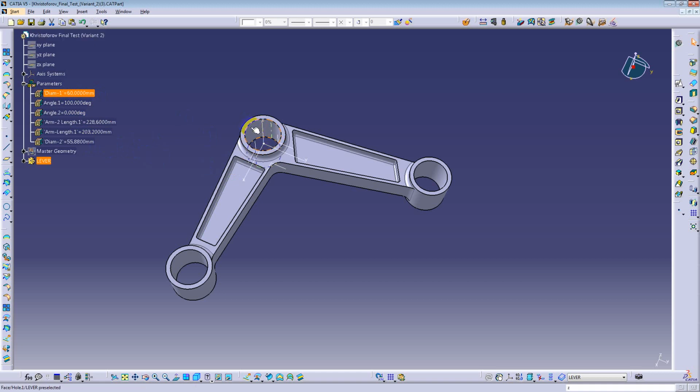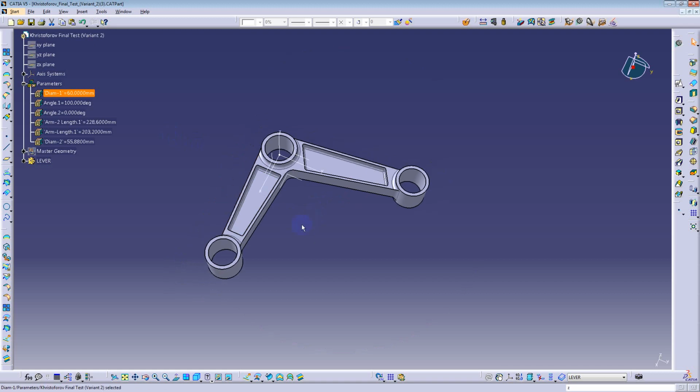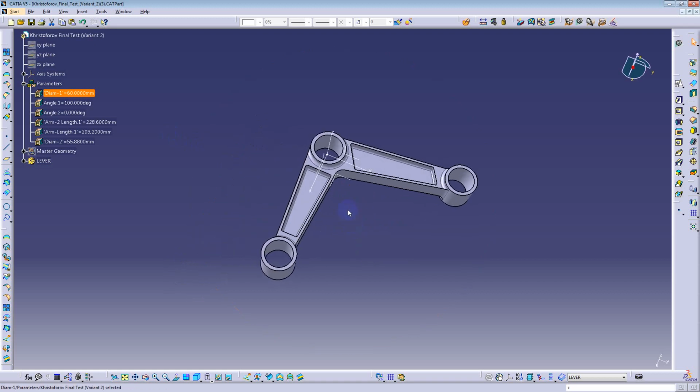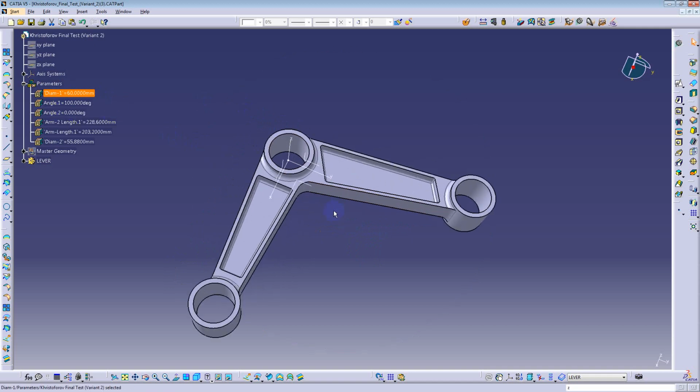It's very useful and comfortable when creating a model, and if you plan to change this model in some range, you can create a parameter, and after finishing your model, you can practice with different parameters and see how your 3D model will react.